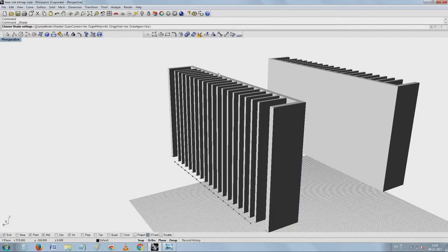the other proportions. If it is rack mounted equipment, usually the front is a 19-inch panel. Inside, what goes inside is, if you take 426 as the width, 19 inch as the width, usually if you leave 20 mm for the flanges, remaining happily goes inside the rack. These standards you need to verify, you should not take it from me. So, if you verify the standards, you will know the width.